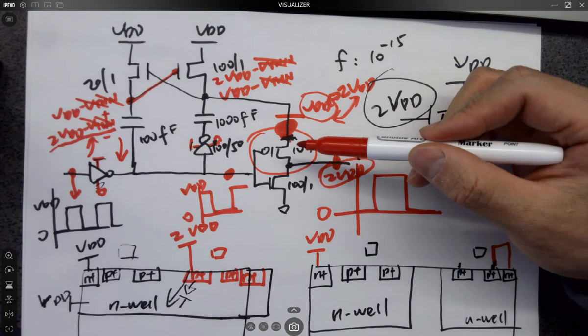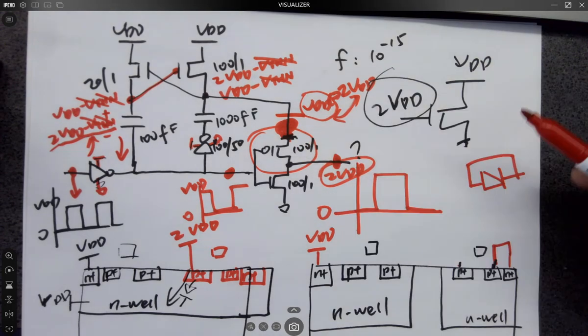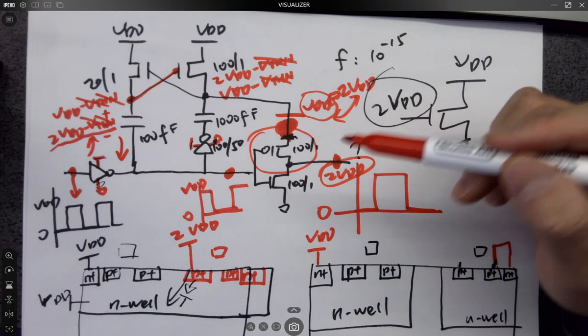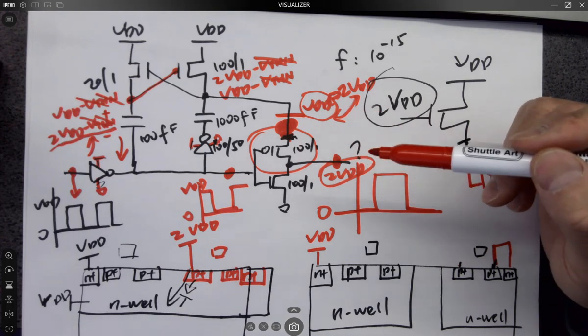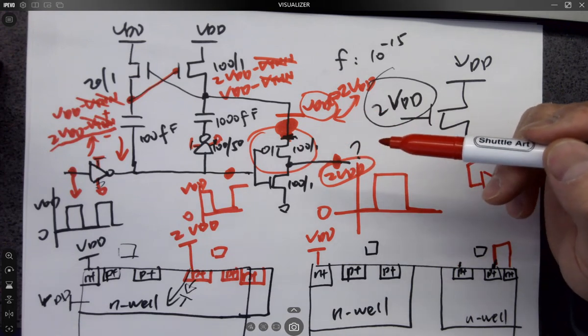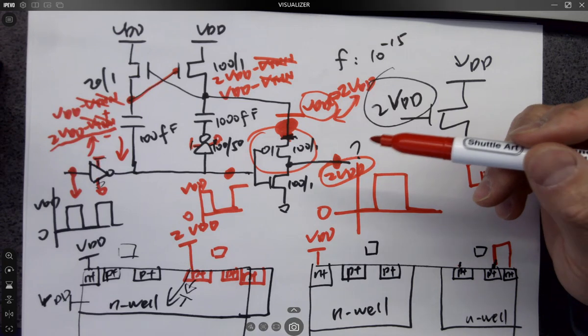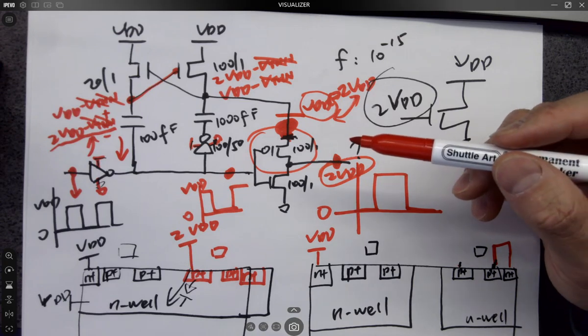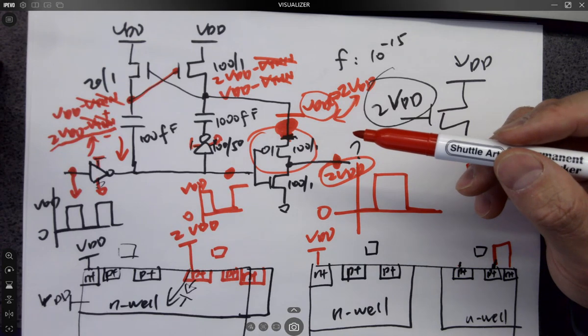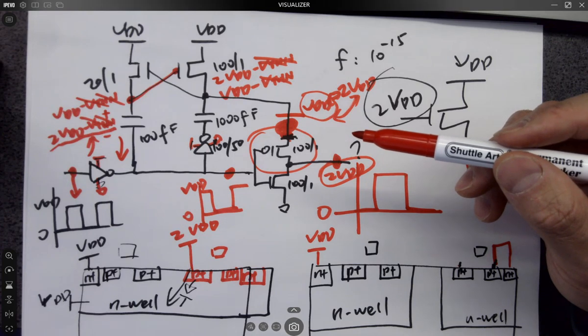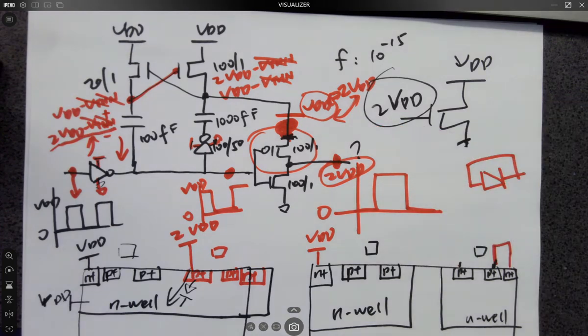In your Electric VLSI, most of the devices don't have the force terminal, right? During the first lab, I think you learned how to introduce the force terminal, which is the body of the transistor. But after that, we all assume the body of the PMOSes is shorted to the same node, which is VDD, and the body of the NMOS is shorted to the ground.